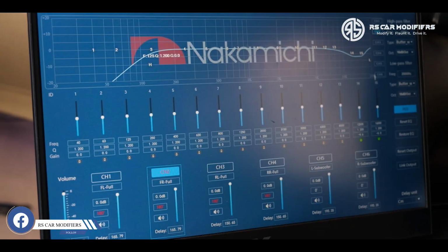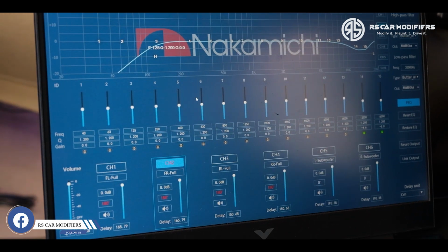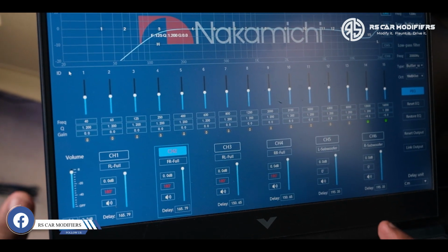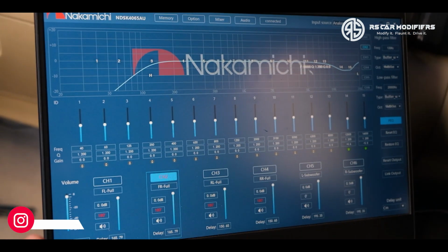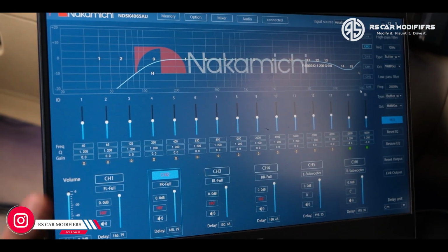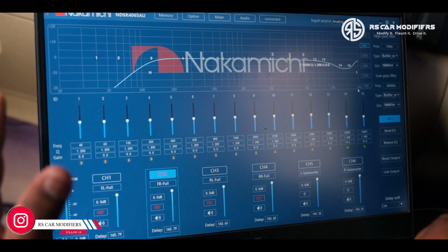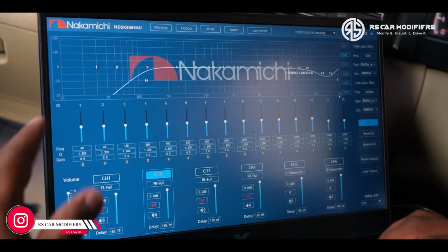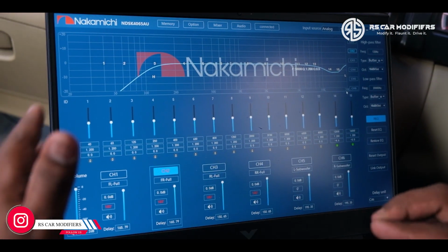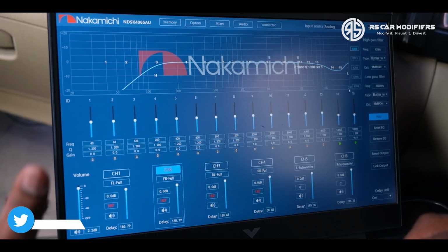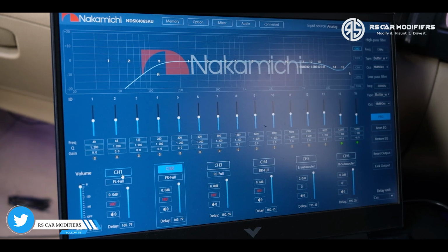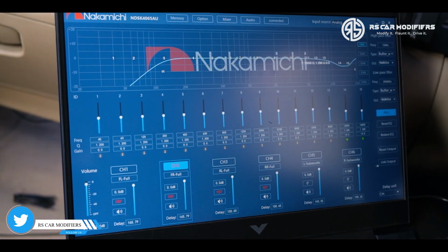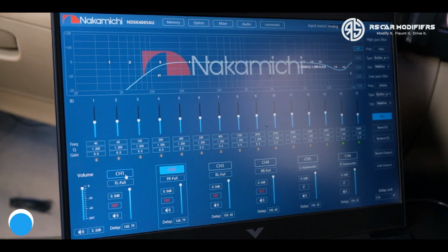So what is a DSP going to enhance? Basically with a DSP, we can tune the audio signal in the range of 20 Hz to 20k Hz. We are going to set up the crossover frequencies required for the speakers and also the crossover frequencies required for the sub. As I have already said, there are channels 1, 2, 3, 4 and 5, 6. So let us start with channel 1.